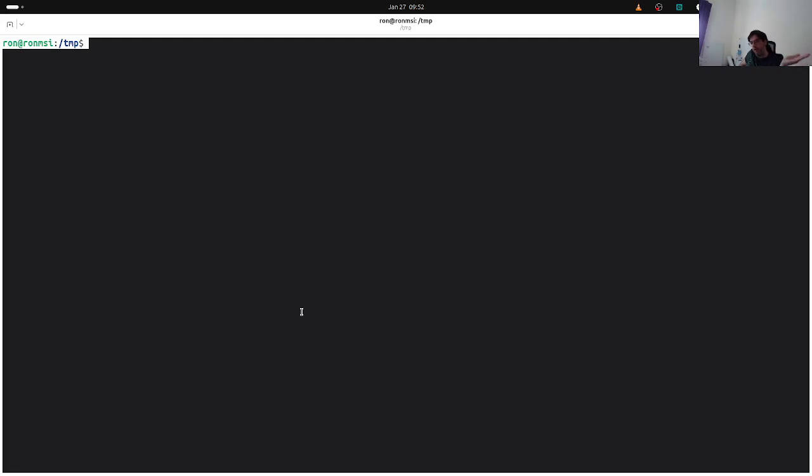And we also know that once we wipe the eMMC and force the device to not boot to it, which is the more elegant way, the other ways would be to desolder the eMMC, or to glitch the eMMC and make sure that it's not identified or that the bootloader cannot properly read from it. Once we do that, and we have an SD card that has the right bootloader, which is what I built, and I have it on the PscgBuildOS, and I have another open source project that shows how to build that, it explains it.